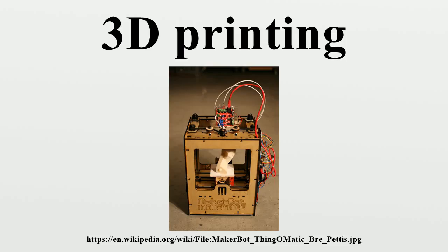Typically, stepper motors or servo motors are employed to move the extrusion head and adjust the flow. The printer usually has 3 axes of motion. A computer-aided manufacturing software package is used to generate the G-code that is sent to a microcontroller which controls the motors. Extrusion in 3D printing using material extrusion involves a cold end and a hot end.